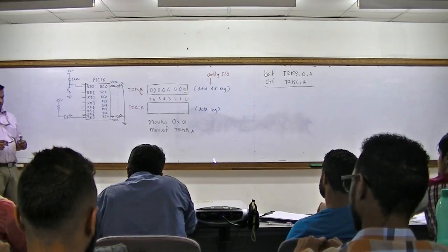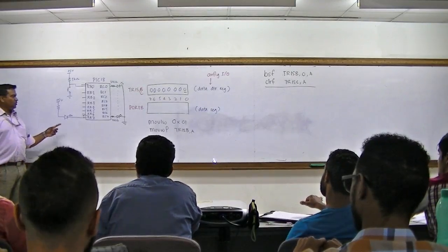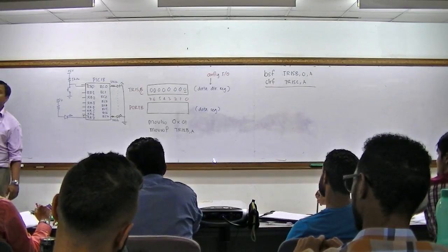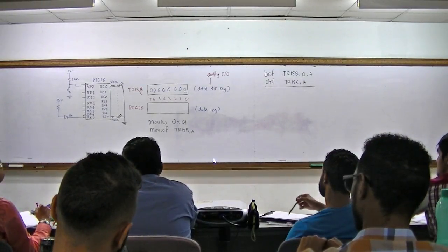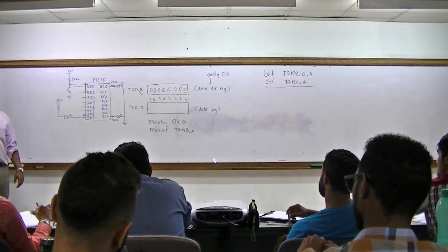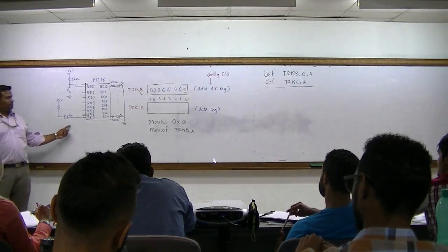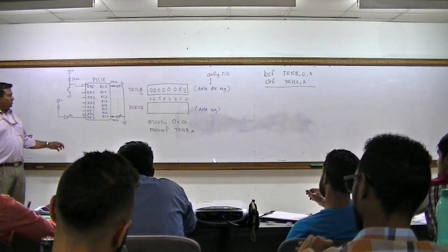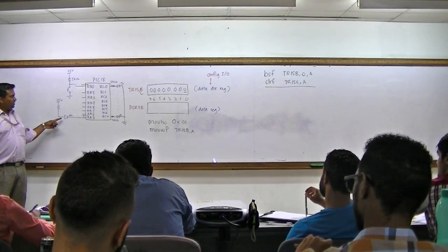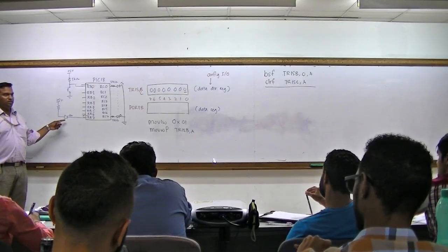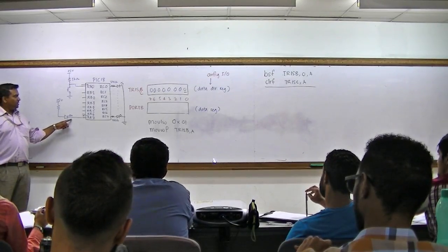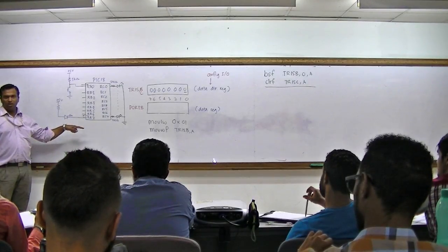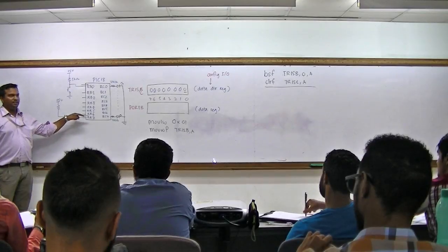Can this configuration of the LED be used? Yes, it is the reverse way of doing. Actually, this one is more popular than that. Here you are supplying 5 volts to the LED, and this pin must be 0 in order for the LED to turn on. So this allows the current to sink in.